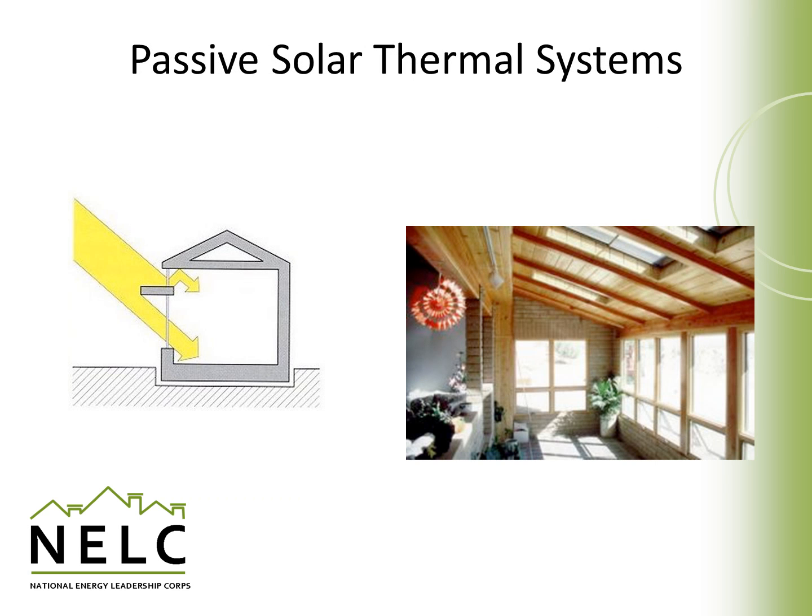In passive solar systems, the sun is allowed to penetrate inside the house and help heat the house without use of mechanical equipment. Passive systems usually make use of high mass materials that can store the heat and help distribute it over a period of time. And they're usually supplemental to other forms of heating systems in case there's not enough sun to provide the needed heating in the house, but they can often provide a significant amount of energy to reduce the use of fuels in the heating of a house.